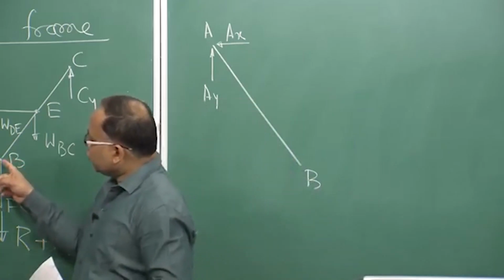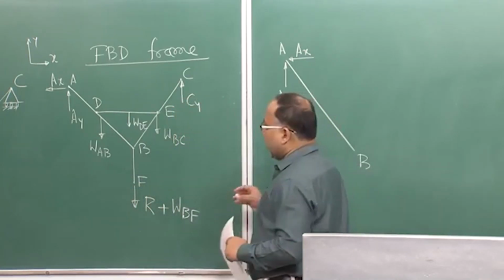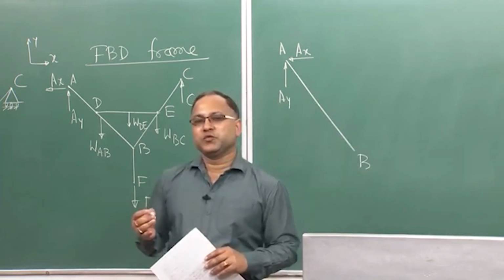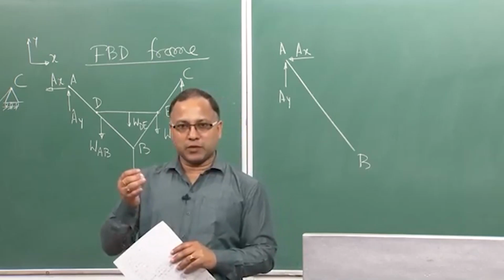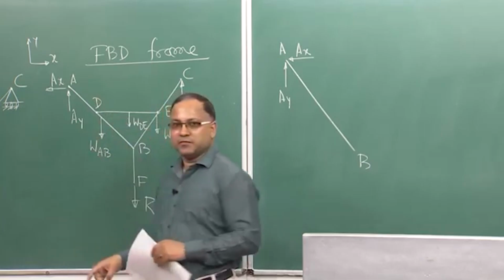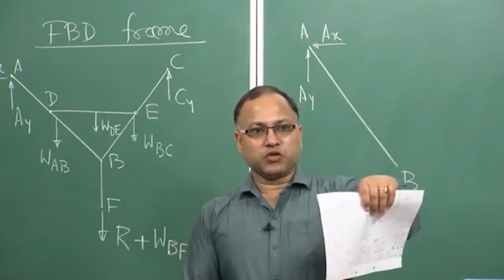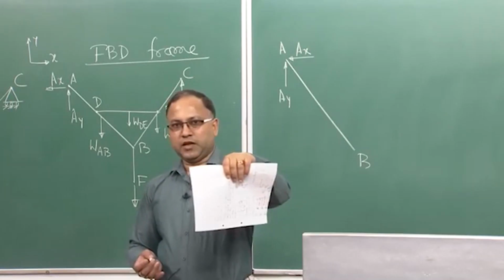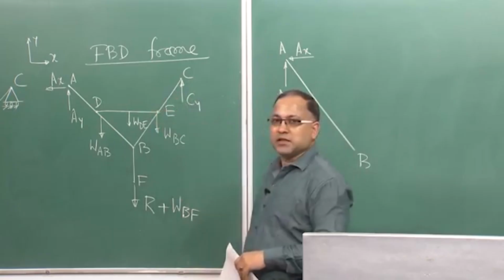Now, this is a joint, as I told you, B is a joint. Now, I do not know the direction of the force at this joint, because the joint is giving some support for the member AB. AB is getting held by these 2 supports A and B, right. So, at A I have defined the forces, because that is the hinge support.